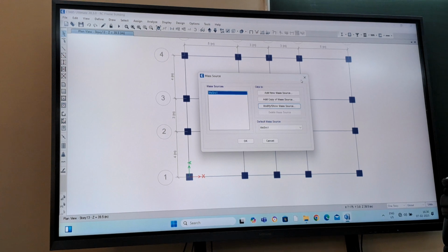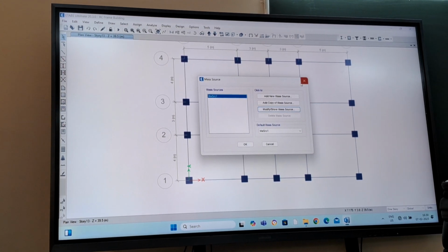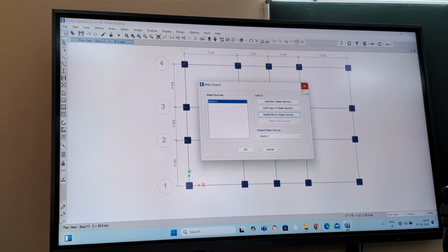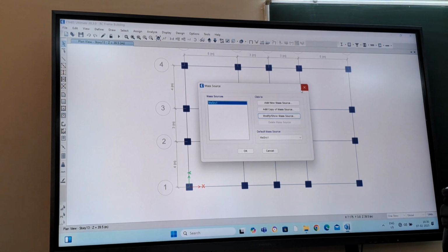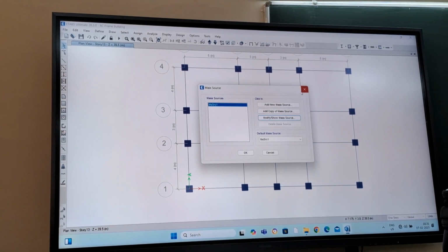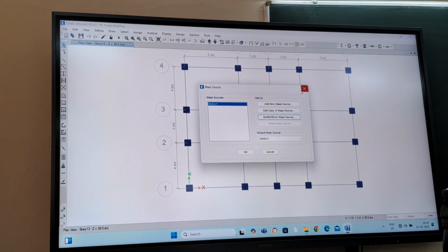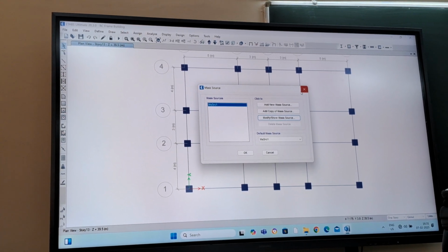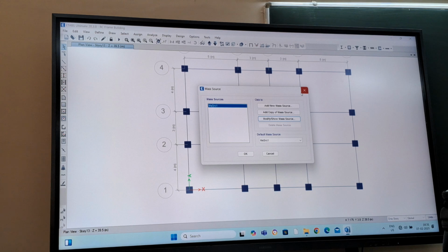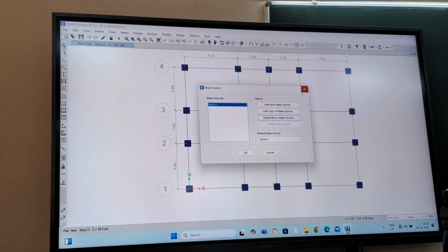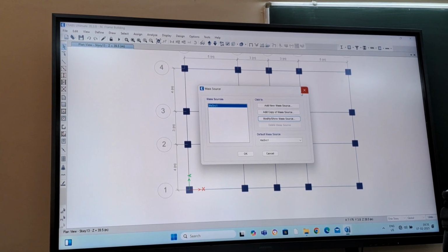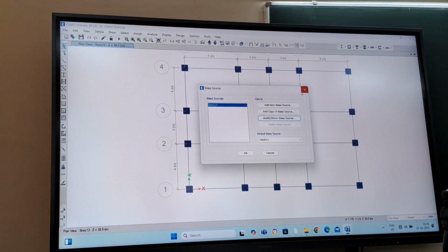Anything else? Sir, when you were designing and you mentioned about the axial failure, we had to put columns individually and then change the position. Yeah, that is the most ideal condition. You go to each member, then provide suitable sizes, then check again. But if you have a small model, it is possible to go to individual members and provide the sizes. It's very much difficult for complex and large structures.